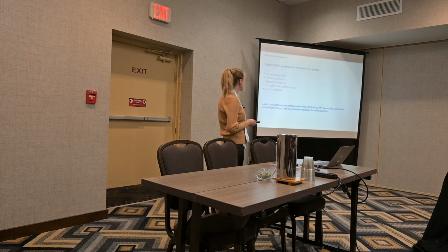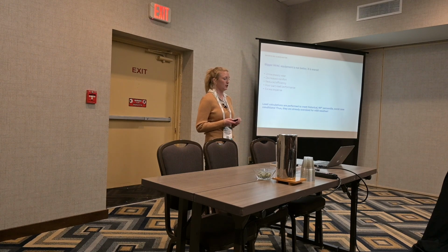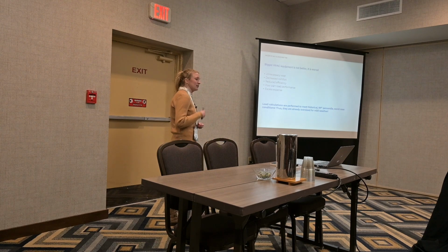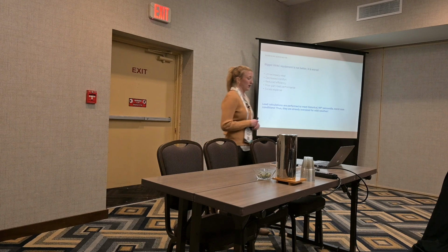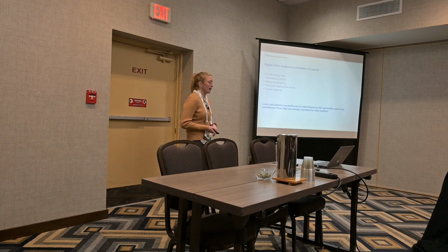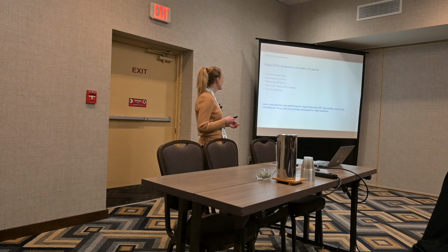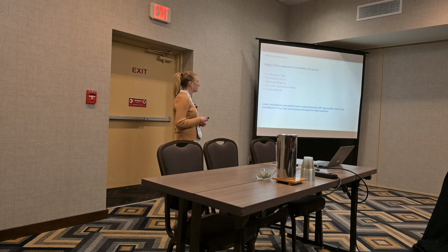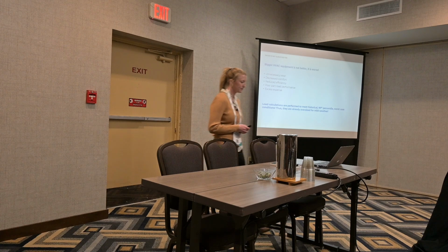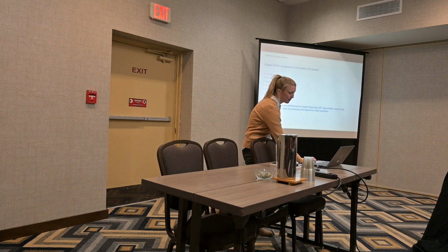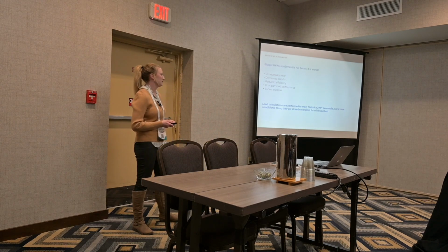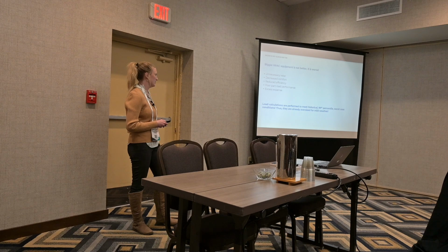So what often happens when you use a rule of thumb, we often oversize the equipment, which especially when it comes to heat pumps is not going to make things better, it's going to make things worse. Oversized equipment, whether it's a heat pump or a fossil fuel fired piece of equipment, is going to cause excess wear, decreased comfort, reduced efficiency, poor part load performance, and excess expense for the homeowner. Load calculations are performed to meet the 99 percentile worst case conditions, so it's already oversized for mild conditions as is.